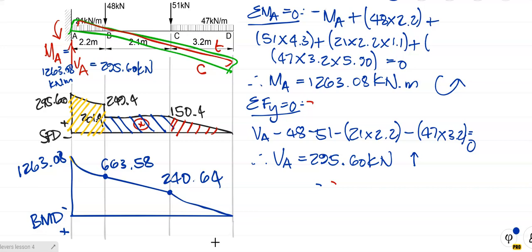Okay, and our bending moment diagram is finished. Okay, and notice there it's all negative. So what can you see there in the shear force diagram for a cantilever? If it's got only loads at the top there, the shear force diagram is at the top of the 0 line, and the bending moment diagram is at the top of the 0 line. So can you see how different it is from a similarly supported beam?